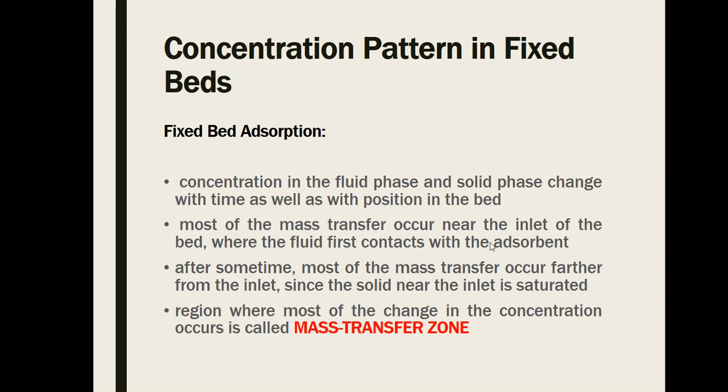This is a given. It's because the adsorbent in the inlet is not yet exhausted at the very first time that the fluid enters the bed. Since it is in the inlet that the greatest uptake of the component solute from the fluid is observed, this particular pattern repeats itself once the solid adsorbent in the bed is already saturated or exhausted.